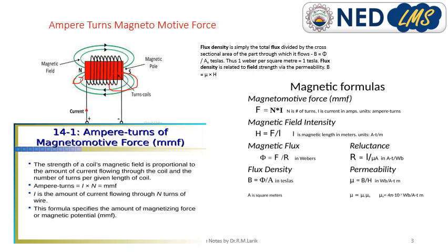For example, in our step down transformer, the primary coil's number of turns is more than the secondary, because it is step down. On the secondary side the voltage steps down to some value, so there is no need for the number of turns to be greater on the secondary side. The primary side has a greater number of turns because it deals with more voltage, and the secondary side deals with low voltage.